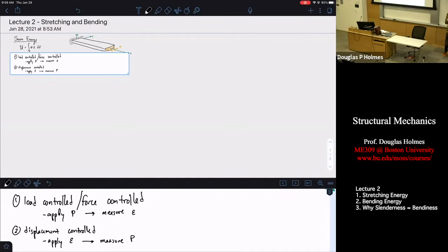The behavior of that soda can will be remarkably different if you apply displacement control, in which it will still buckle, but it will not crush. It'll just slowly develop these little crush-like patterns around the ring of it. It'll be stable in those states all the way until you load it into its little pancake. Most of us, when we crush a soda can, we apply a load. We literally step on it, or we stand on it,